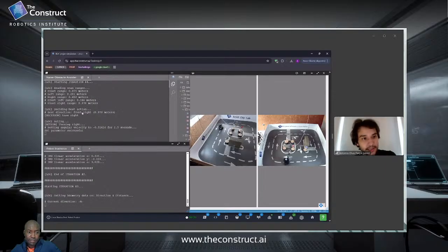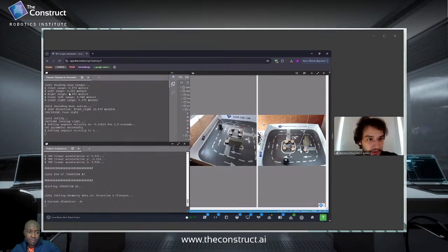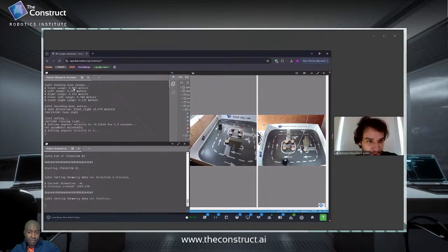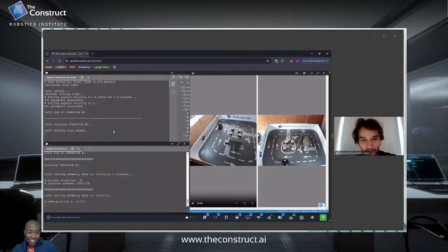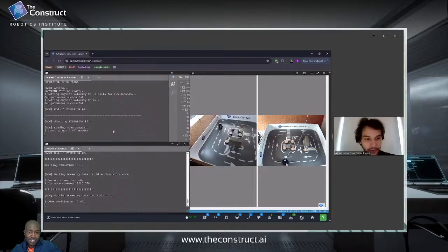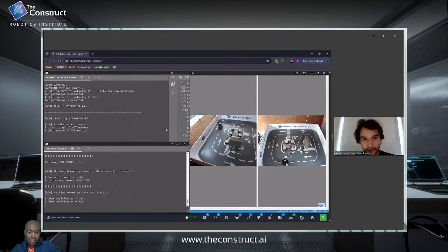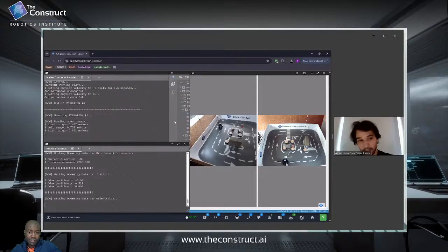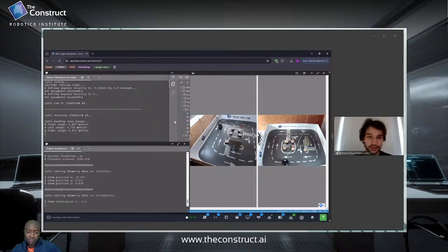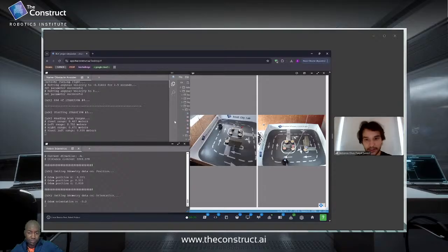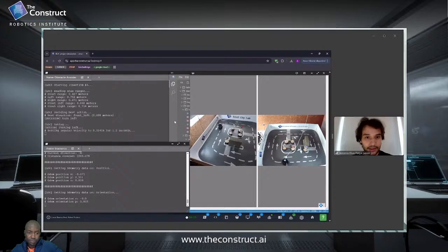Well, it is detecting that front right is apparently the best direction because it's like 0.003 meters freer than front. My logic is based upon a simple algorithm of just turn left, turn right, or move forward. If it detects that the best direction is front left or left, it turns left, and the same goes for right. It just moves forward if the best direction is front.